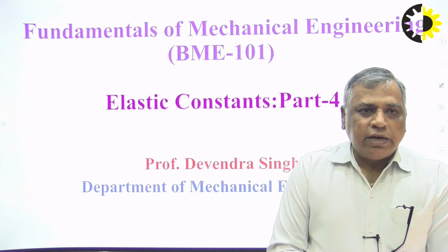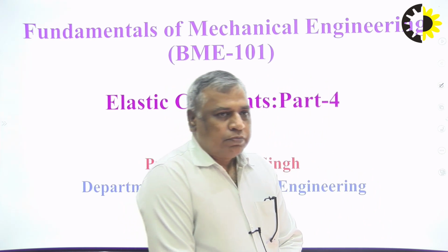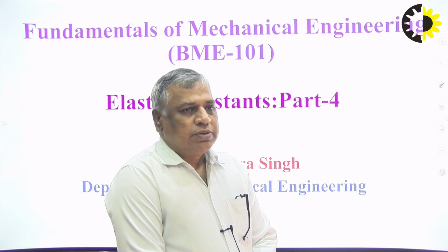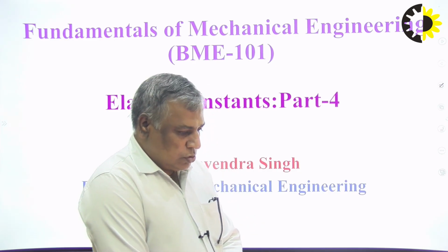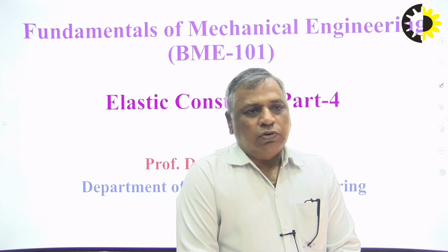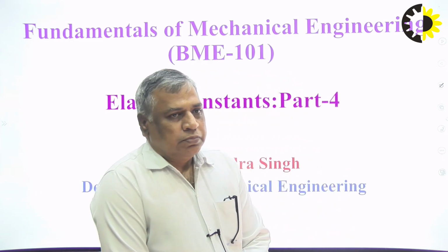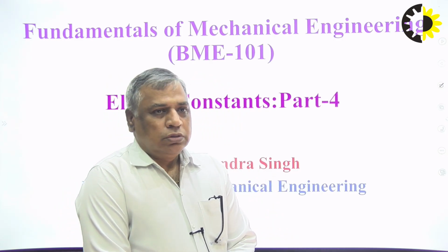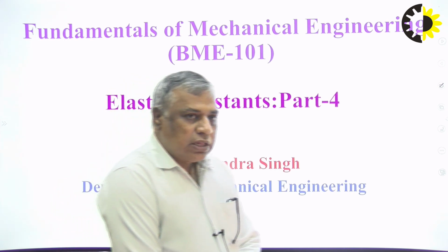In the second problem, we were given data from a test performed on a universal testing machine, and we were asked to find the modulus of elasticity, the percentage of elongation, and the percentage of decrement in the area. For that, we used Hooke's law, which is valid up to the elastic limit of the material.